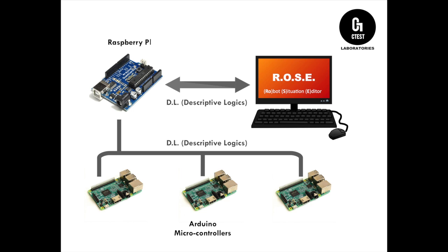Occasionally, in some situations, we do have hardware sensors hanging off of the Raspberry Pi. For instance, we might have our camera. I know we're using a Pixy camera off of the Raspberry Pi on one of our robots, and I think there's an ultrasonic sensor that sometimes hangs off of that as opposed to on the Arduino. That was just a matter of the kind of processing that we wanted to do, especially when it comes to image processing. It made more sense to do it on the Raspberry Pi than on the Arduino microcontrollers. So this is the high-level picture.